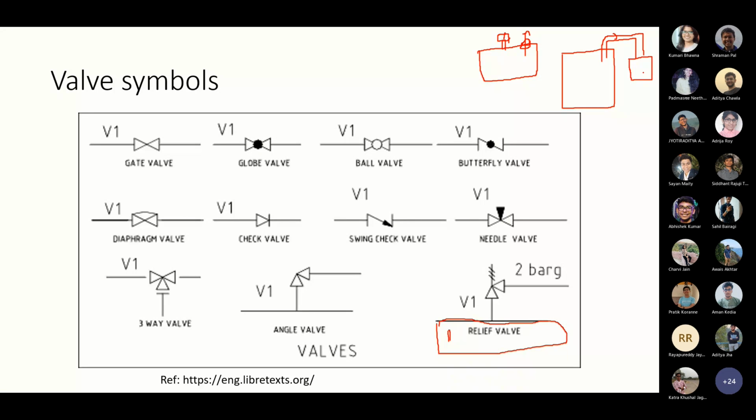So as soon as the pressure or the temperature increased, the relief valve opened and all the vapors came up suddenly and formed a cloud mist around the Visakhapatnam area and caused a lot of trouble. So that is where this relief valve is helpful. The relief valve helps to protect from major damage, especially damage to the process vessel.